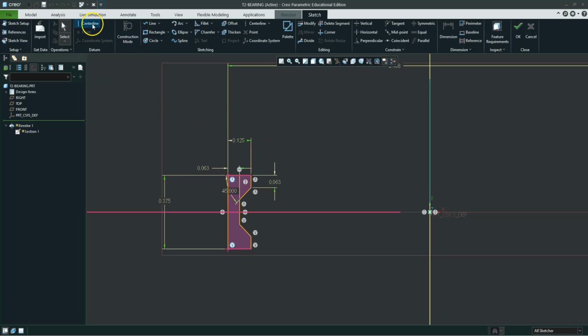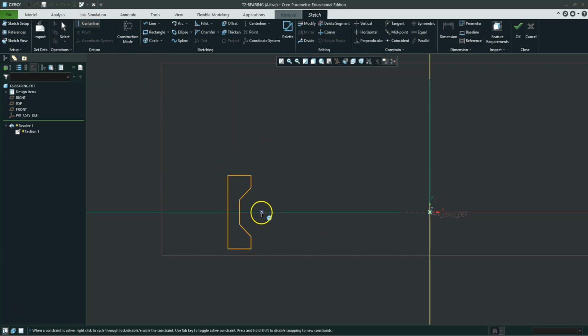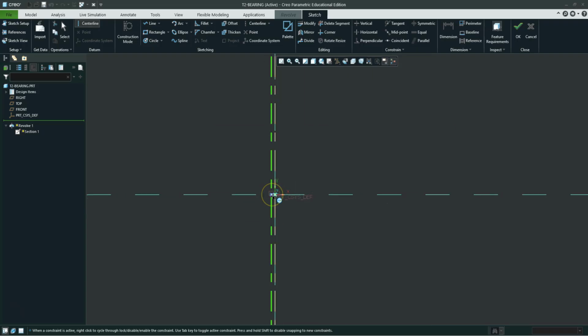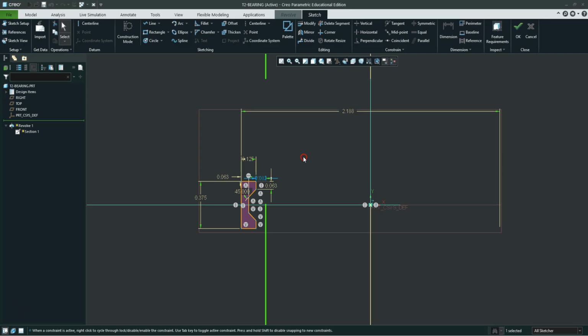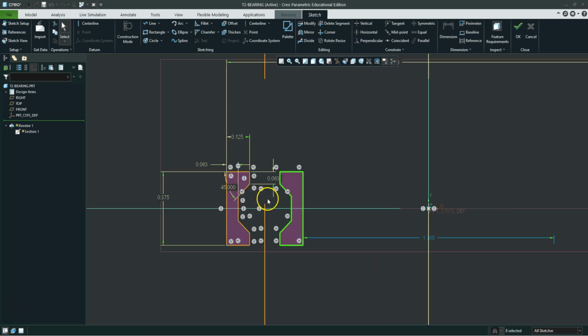All right, so we're going to pick Centerline again. This time we're going to hover over that horizontal line instead of the center over here, and we're going to click a little to the right of where our first sketch was. We're going to click, and then we're going to make that line go vertical like this. Okay, and depending on the scale you're at, you can see mine's sort of changing a bit, but that's all good. My center line's there either way. And then by clicking over here in the same area again, we're going to highlight all that stuff, draw a big window around it, and we're going to say mirror again, and we're going to mirror across that line I just created. And that creates the other side of our race.